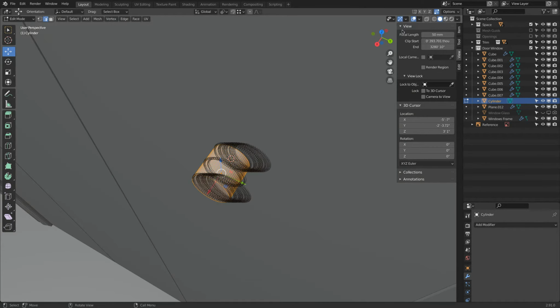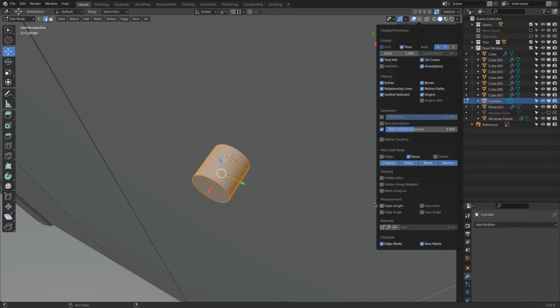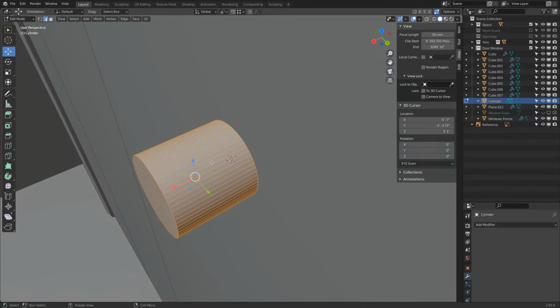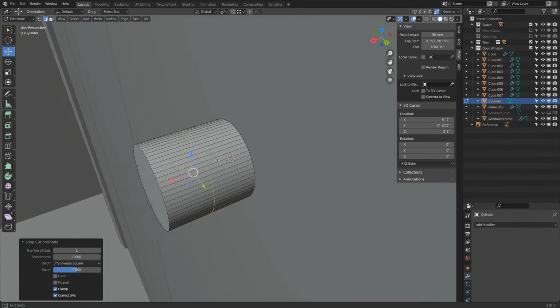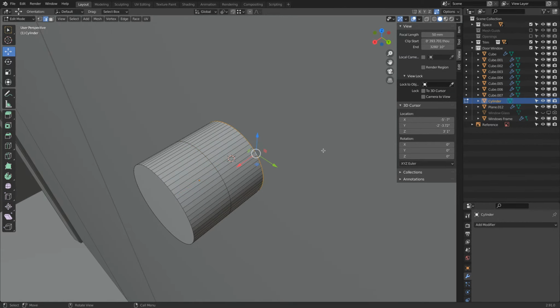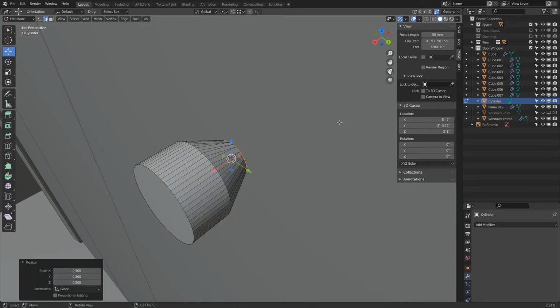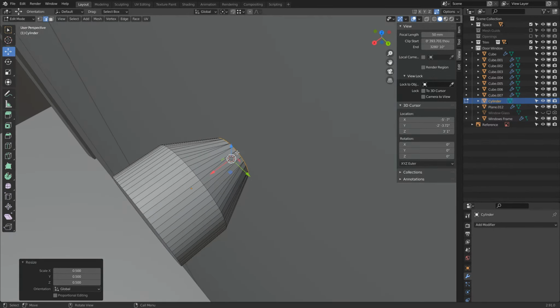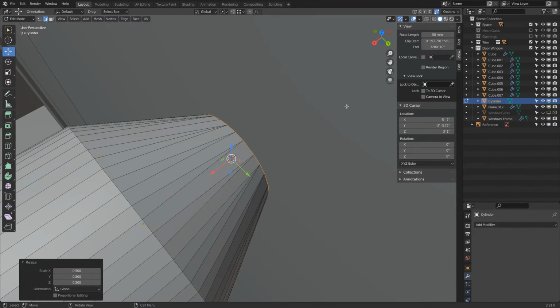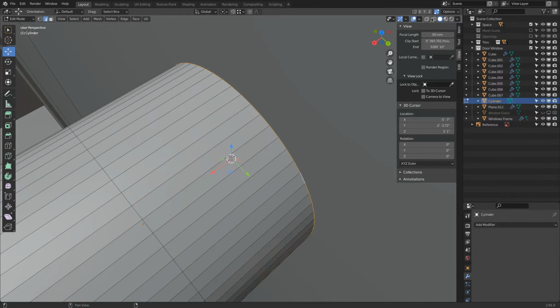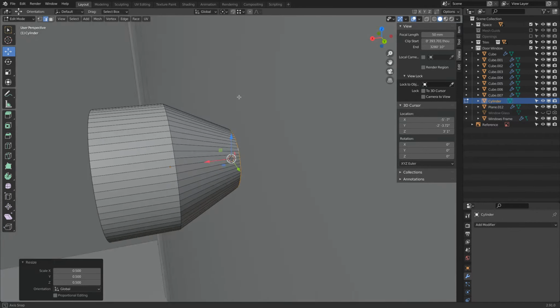If we want to style this a little bit, like for quick visual reference, Control R. Okay, select this, back to bounding box, S and 0.5. So we scaled this down actually 50%. And oh, what's happening? Oh, I have this here turned on. It simplified the geometry. So undo, turn this off, S 0.5. So we scaled it 50% down.